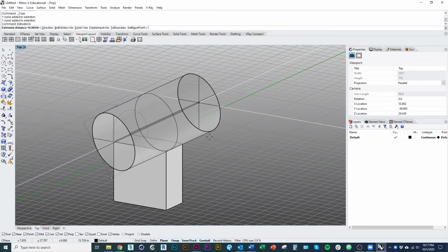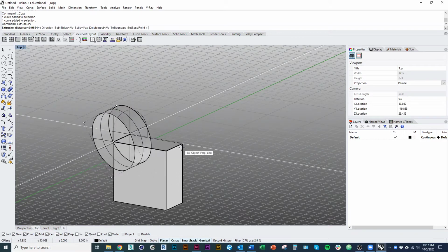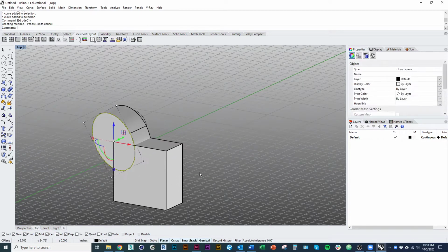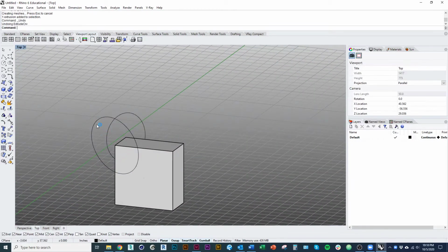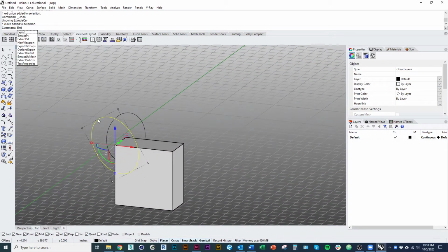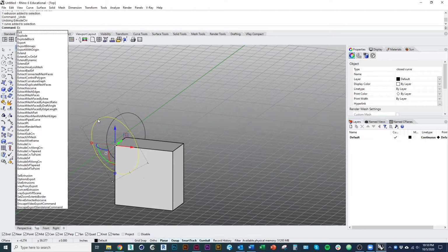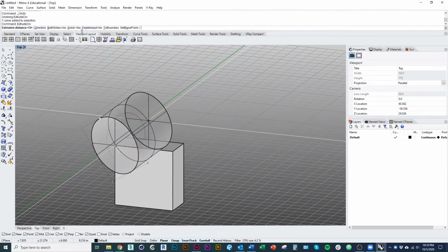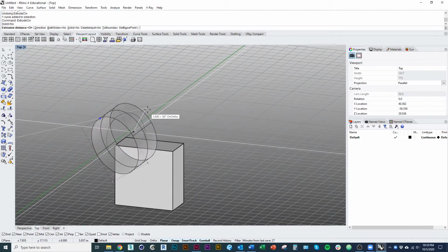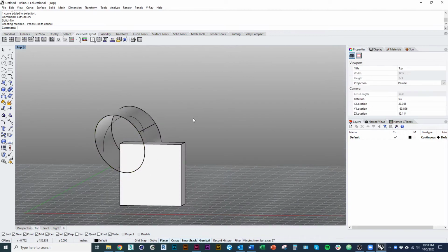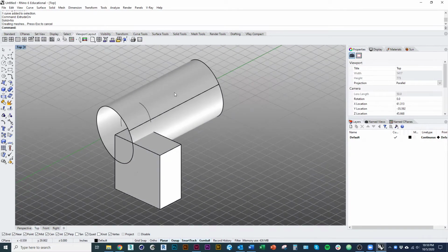And that will allow me to change any closed outline into an extruded closed volume. Just like that. Again, when I do that, extrude curve, the option solid is set to yes. When I set the option solid to no, oops, you can see I just get an open tube, right? Which is not what I want. I want it to automatically close my object, make it a closed volume.